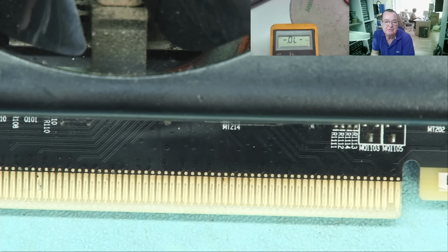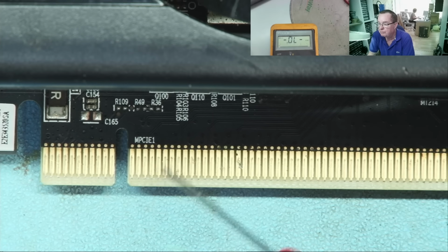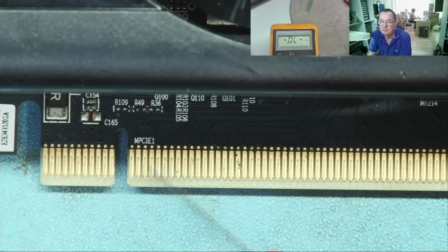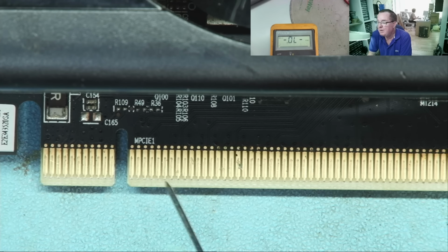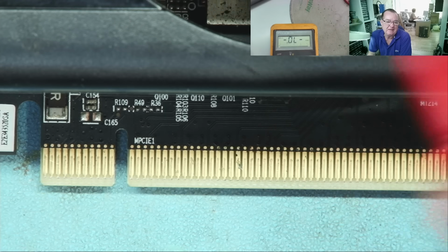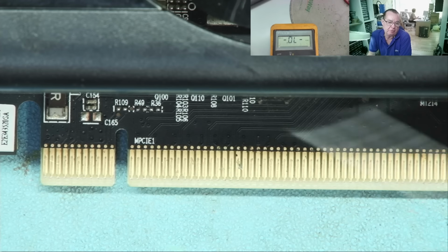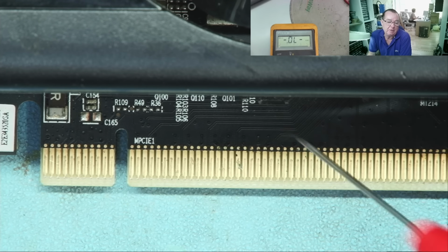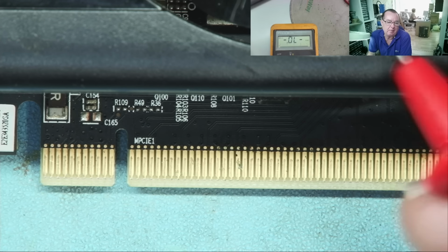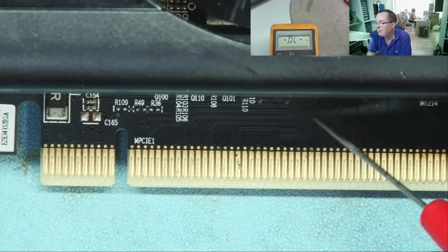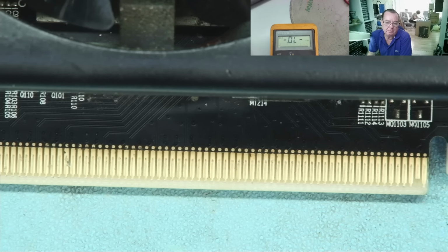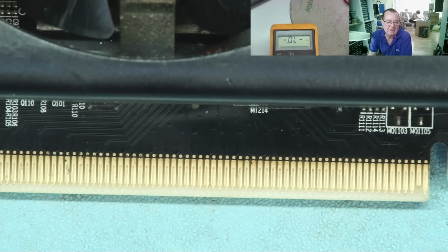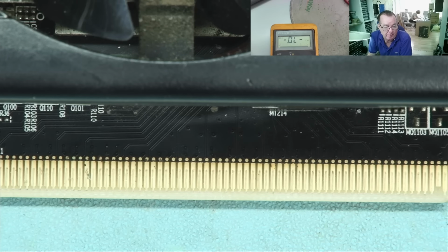So they all read basically the same. The one that's most likely to be damaged, if any, is the first one because of this business with mining adapters, okay? But it's worth checking all of them, because if there's any internal damage to the GPU from some other reason, not because of a mining adapter, you may find one of these that reads open circuit or something like that. And if you find that, then the problem is in the GPU, or it's a broken track going up here to the GPU. Most likely, when I say broken track, it's a broken BGA ball underneath it, which is not the easiest thing to fix anyway, but at least you'll know what the problem is.